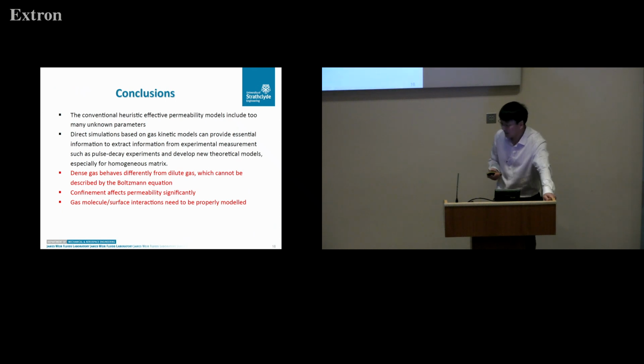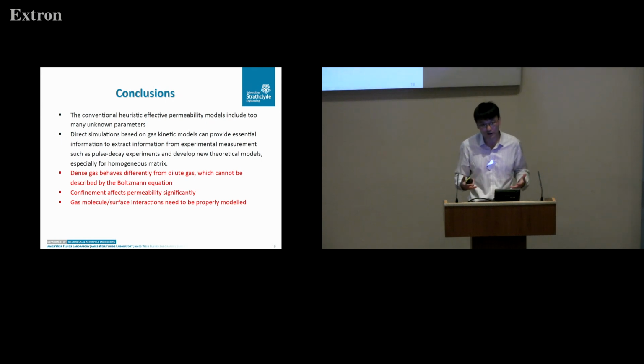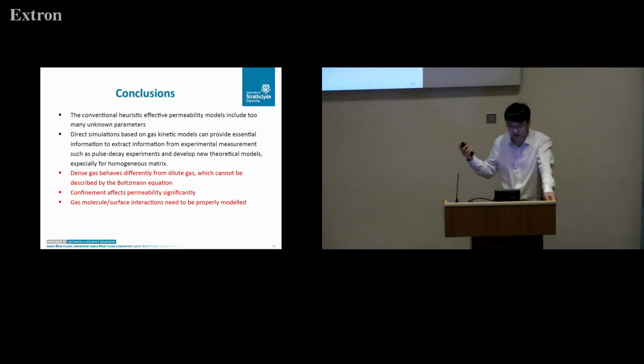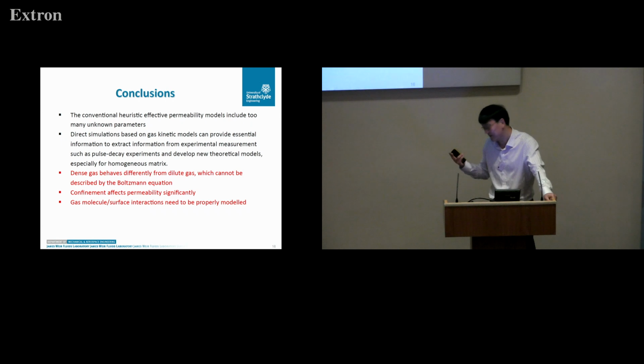Finally, my conclusion is that to develop proper flow models, we need to resort to gas kinetic theory to have a bottom-up approach. At the moment, we need to develop a proper dynamic boundary condition for the gas kinetic model. And for the dense gas model, the simplified Enskog type model, we really need help from experimentalists to validate. This is extremely difficult, I found.